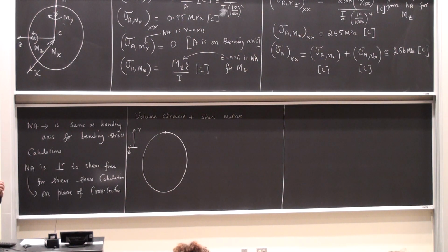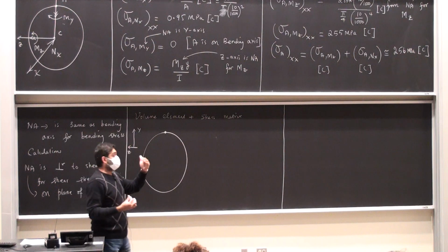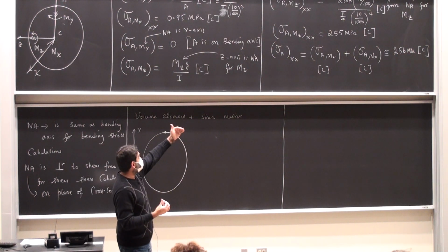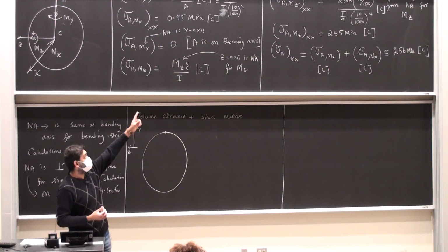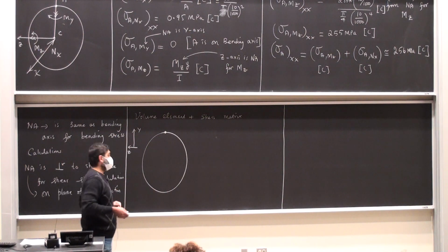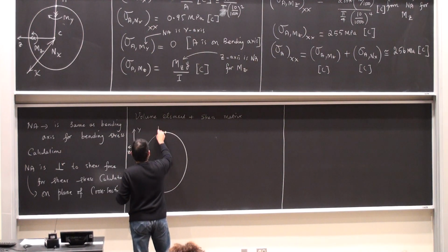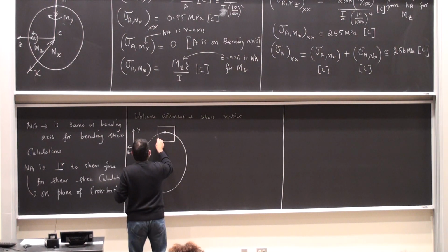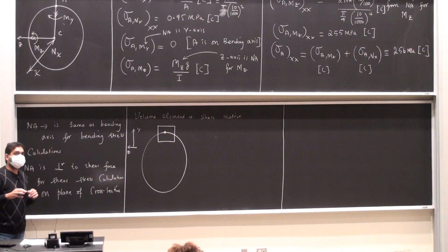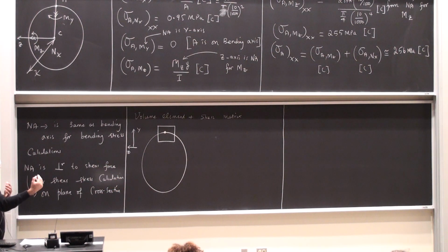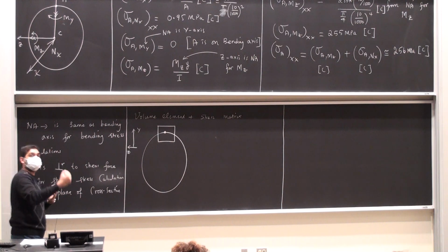At point A, the direction of the shear stress is going to be pointing to the left. We just decided that was the case, right? The last panel on the top there. So draw a volume element, so draw an area element, just a rectangular box. First draw the direction of the shear stress, which is going to be pointing to the left.